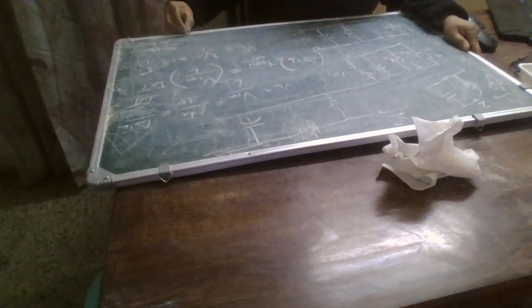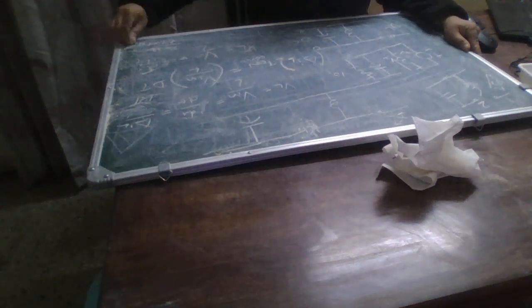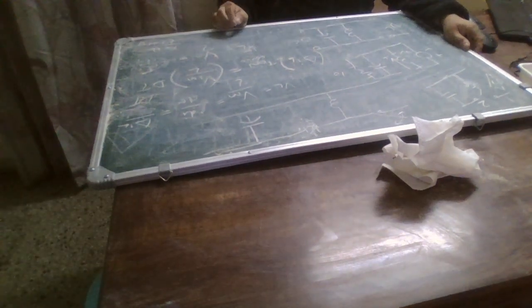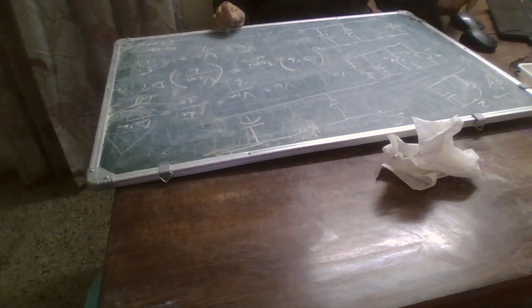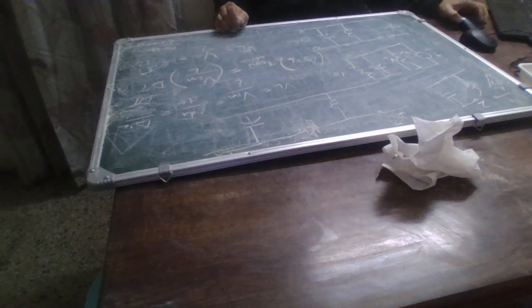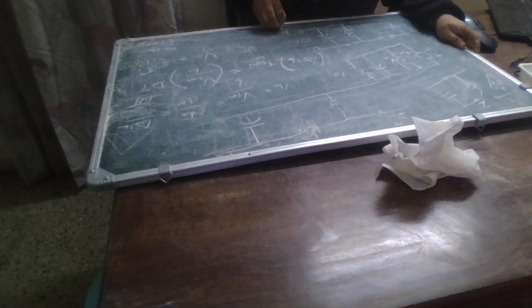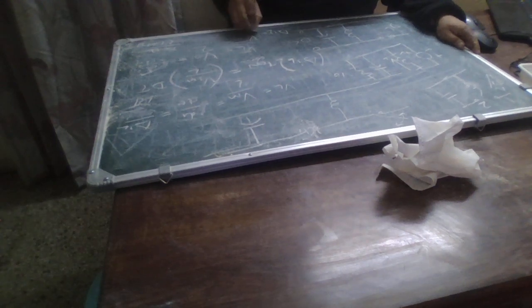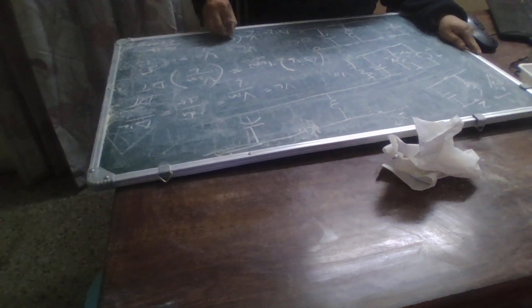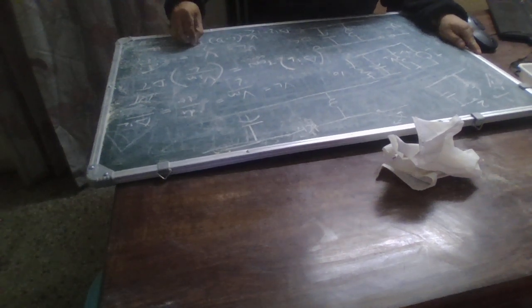Now we know that it's off for the time 1 minus d, times T. All this on and off time duration has been similar for the buck, the boost, all these modes and configurations. The switching time cycle is dT and (1 minus d) T. So we can very easily find here that delta IL is V naught upon L into (1 minus d) T.